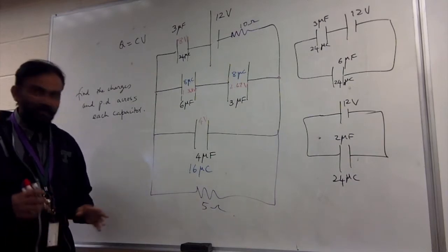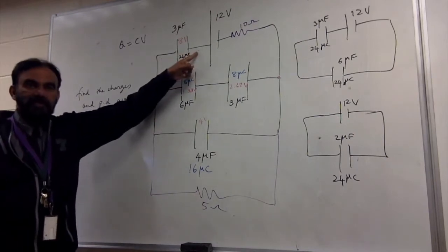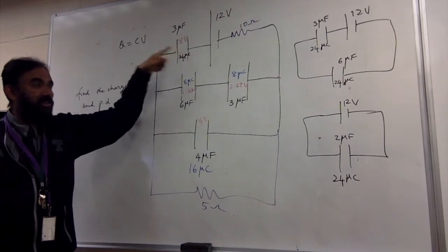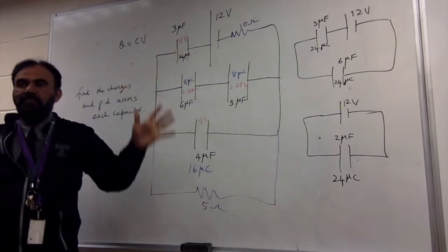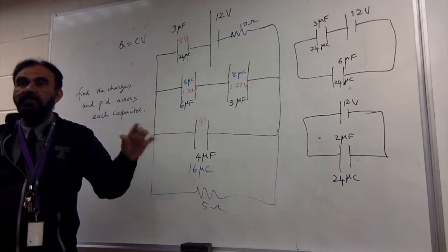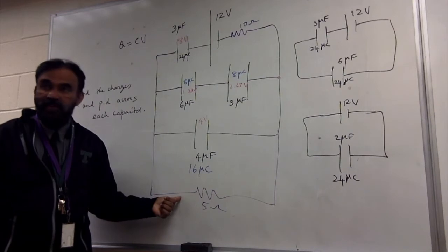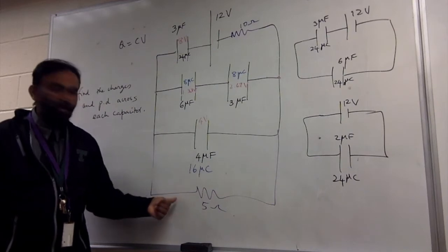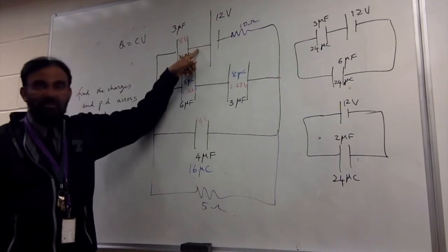Okay, let me help you out here. Yes, there's a current going to flow here, right? Initially. And that's what is charging this up. What is supposed to be the current when everything is fully charged? Nothing? But how can this receive 4 volts and draw nothing? If this is drawing something, that current has to come from the source, which means this current is not going to stop.